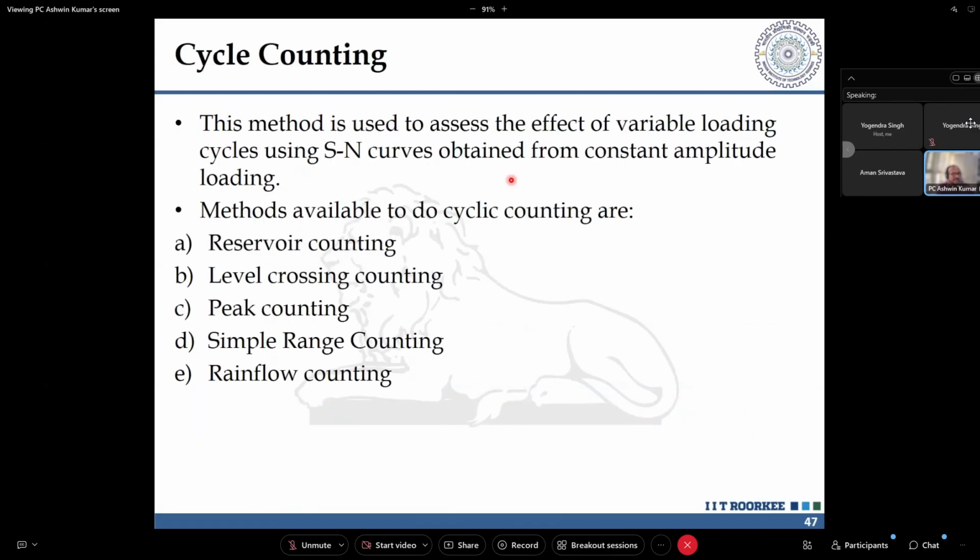And the stress cycle here, there were only 3 ranges. Totally 9 cycles were shown in that particular curve. If a vehicle is moving, there will be a number of stress ranges that is going to come up, and the variation will be very high between the stress ranges. There will be variations in terms of the tension, compression. The cycles might go from one range to the other range. So in terms of that, it will be difficult for us to count these stress ranges to do that SN curve wala thing.